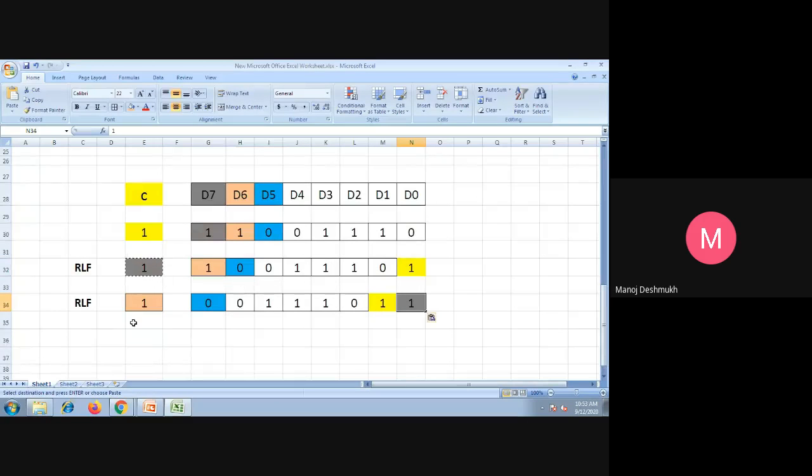So in this way again a second operation is there, but here also we are not interested in getting the status of D6. We are interested in getting the status of D5, whether it is 0 or 1. Again, you have to use rotate left, same. Here this bit comes here, and the remaining bits, whatever the bit is there, will be coming here. So after these three operations, as we know that we want to check the status of D5, that's why